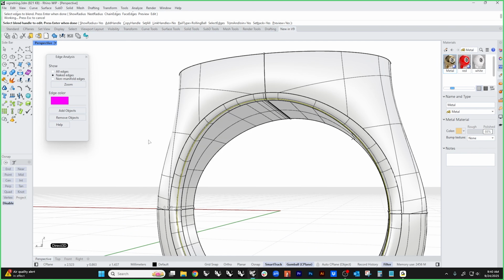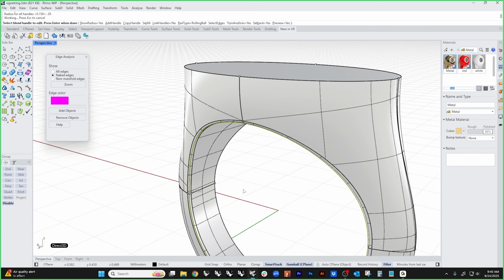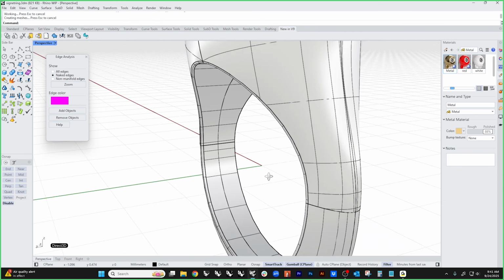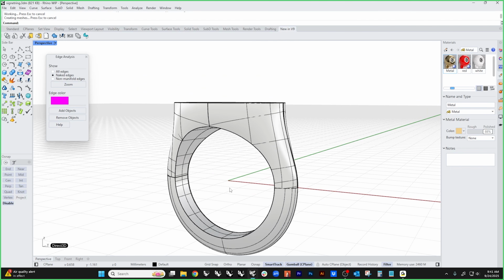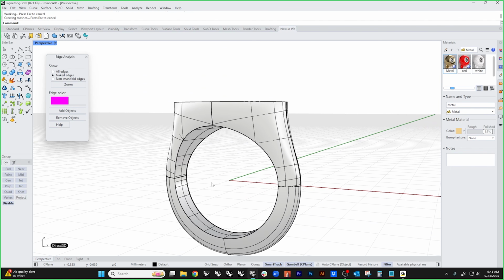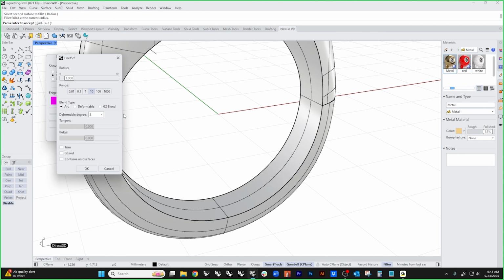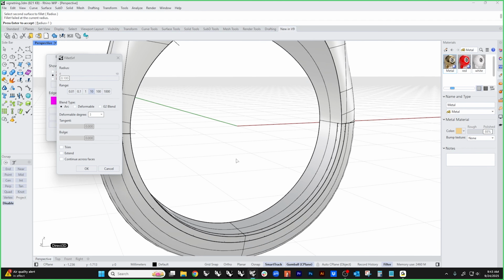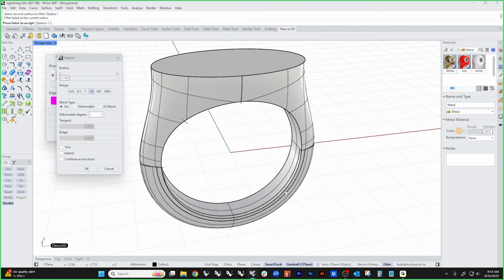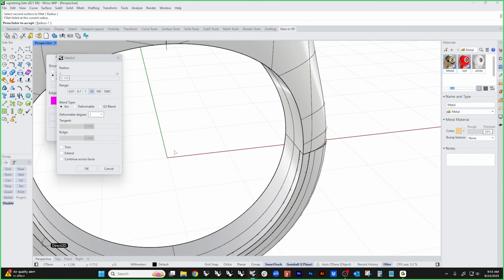Ooh. I want to show you something else cool. You like this. All right, so I'm going to set this to 0.05 or whatever, something really small. Now, there is a new fillet tool in Rhino 9. Well, it's actually just a better version of the old fillet tool, which is Fillet Surf. Let's try this again. It helps if you use a value that Rhino can actually see. Okay, so what you'll see is it put a Fillet Surf in here.